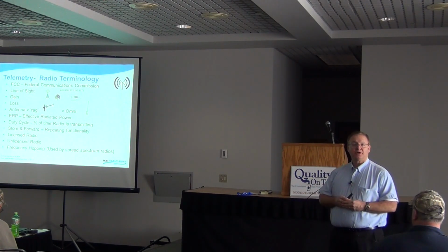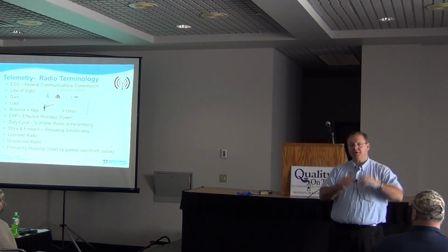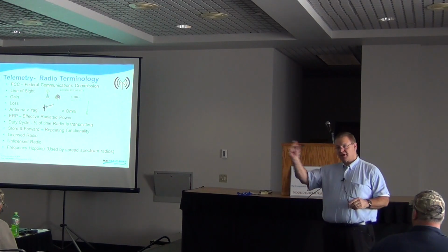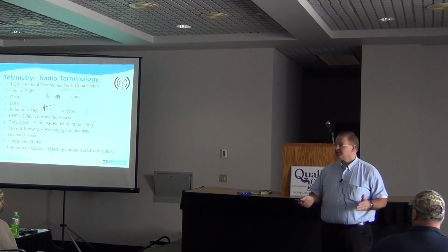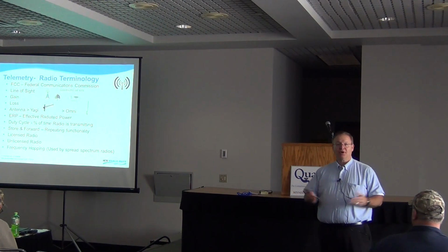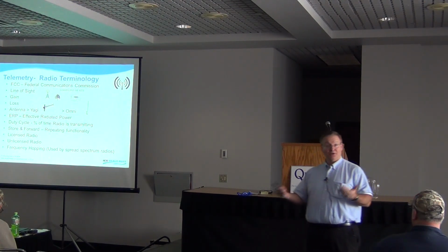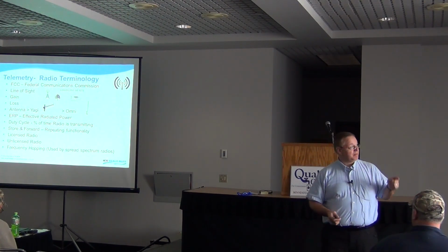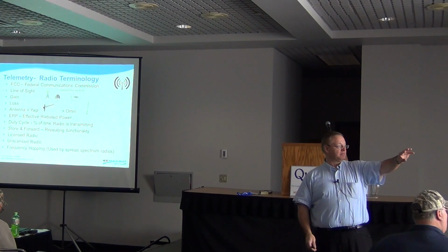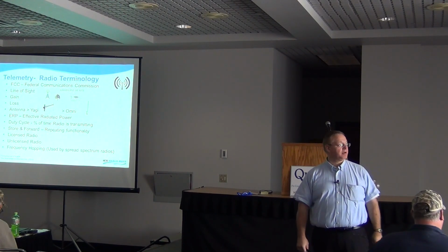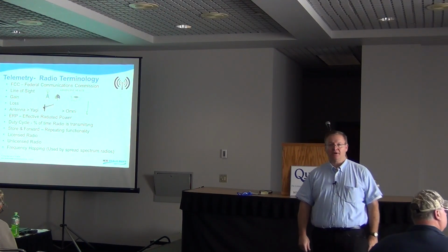Line of sight is commonly used. Line of sight just simply means what it says. The antenna, the top part of the antenna, wherever the radio signal is emanating, needs to be able to see the other top part of the antenna that's at the other site. Some frequencies, the higher frequencies, typically need more line of sight. And when we say more line of sight, well, what is this? Either line of sight or not line of sight. But you'll hear the term near line of sight too. So for me, I can see the top of that tower over there right now, no problem. If there's a building, a church over there that's a little bit harder to see, there's some trees in the way, that would be kind of near line of sight right now.